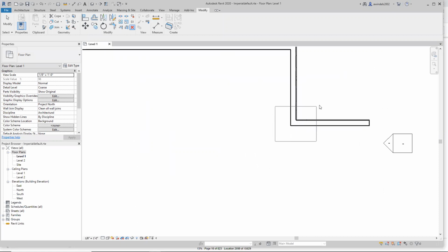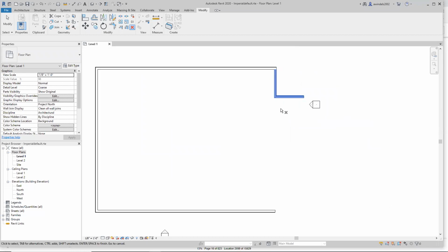So I go this way from the left to the right, it doesn't grab anything unless I encompass the entire object, and it grabs it. Now the opposite is true, and this is just drafting 101, but you're going to figure it out pretty quick. If I do a crossing box from right to left, it'll touch anything, it'll be selected in my selection set. We'll do this.